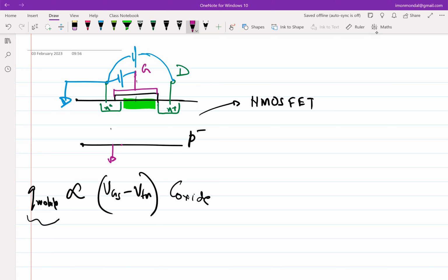But now if you have a doping like this, N+ dopings on both sides, then you essentially have wells of electrons sitting there. Whenever there is a requirement of electrons in the channels, these wells of electrons can supply them. Your device doesn't need to wait for the slow process of generation to get those electrons, right? So essentially, if all the supply which was coming from thermal generation is now coming from source. So that is why you can essentially refer all these voltages responsible for creating charges in electrons in this channel to source, right? And the purpose of body is essentially relegated to ensure that everything is reverse bias. Okay.